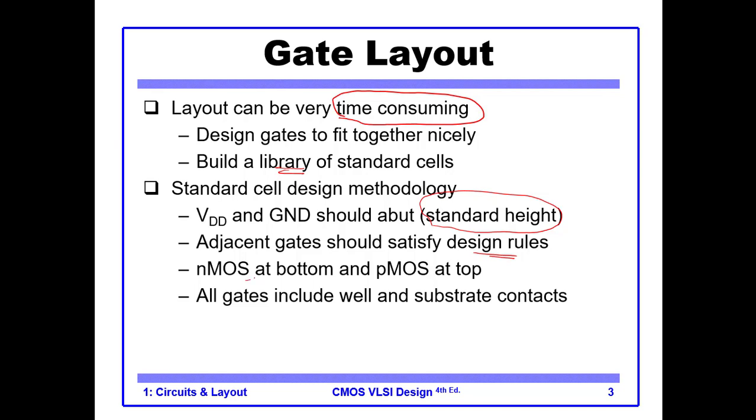And then NMOS should be at the bottom and PMOS should be at the top. Your NMOS are at the bottom near your ground, and your PMOS are at the top near your VCC. Then all the gates must include well and substrate contacts.